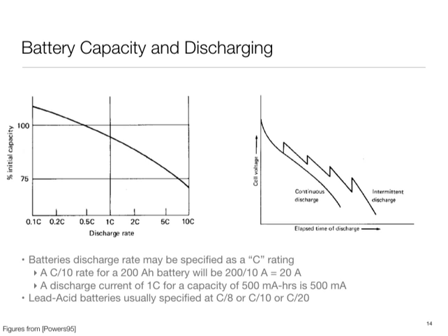What this plot is showing is that if I were to continuously discharge and observe the battery state, voltage let's say, then we'll see some sort of smooth degradation and it will die. But if on the other hand I punctuate the use of the battery, that is, I operate it for a while, and then this jump means I stop using it. When for some time I stopped using it, its voltage jumped up. So it kind of revived. By not using the battery, I'm letting the battery relax, and so it is rejuvenated and can supply energy to us again. These are the two non-idealities that exist in the battery.